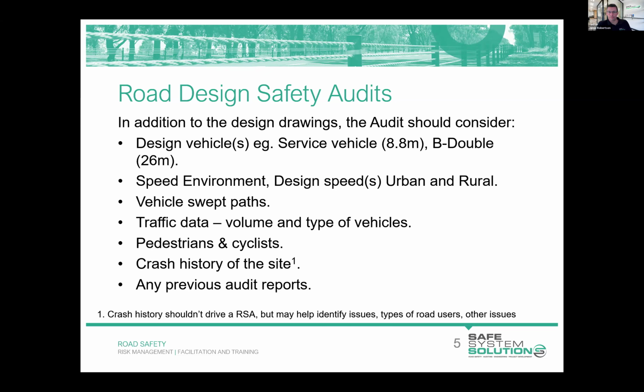What's a design vehicle? I'm sure the road designers out there will know this well, but the design vehicle is basically the largest vehicle that is expected to use the piece of road that we're dealing with on a regular basis. So we want to cater for that vehicle in a desirable way. So the vehicle should remain on the pavement, not encroach curbs, be able to make turns from the correct lane, and so on. We'll later talk about a check vehicle, which is a bigger vehicle again, which we need to check our designs against, but that doesn't need to operate in such a desirable way.